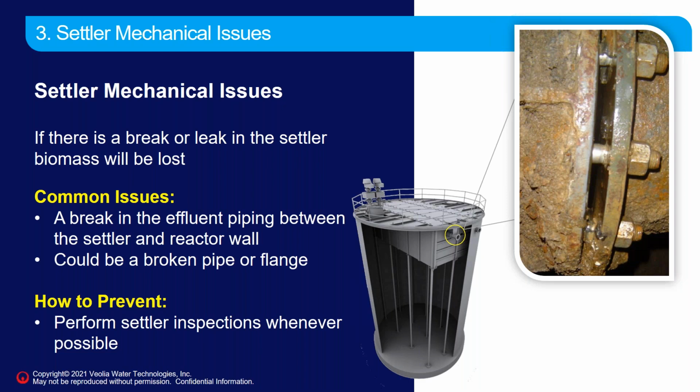Some type of planned maintenance or inspections, tightening these bolts. Our standard is to provide double nuts or lock nuts on any flanged or bolted connections inside a tank. That would help there. If you're going inside the tanks, make sure these connections are tight, and replace the gaskets after several years.